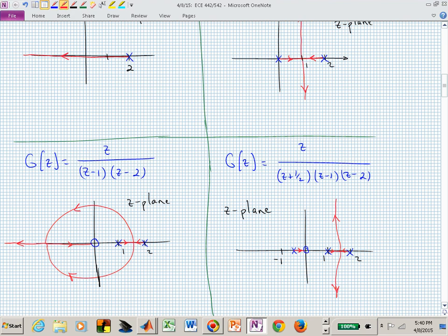So you have one branch that goes off to infinity, the other one stays finite. Look at the next one in the lower right. How many poles do we have there? Open loop, how many x's? That's kind of a hard question, isn't it? There's 3. How many finite zeros do we have? 1. What's the pole-zero excess? 2. So now how many zeros at infinity do you have? 2, and so you would expect 2 branches to be going off to infinity, and in fact they do.